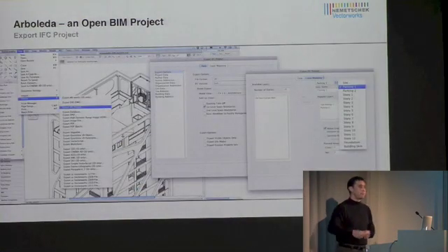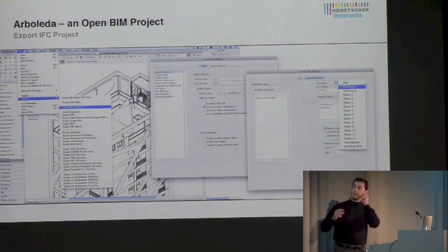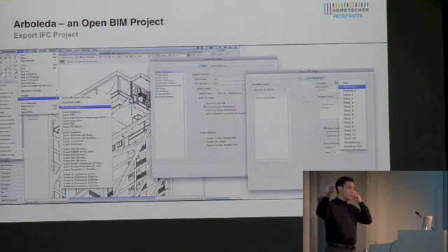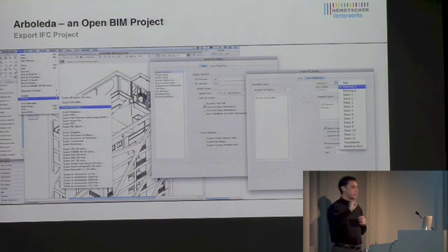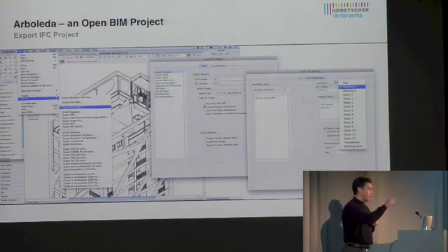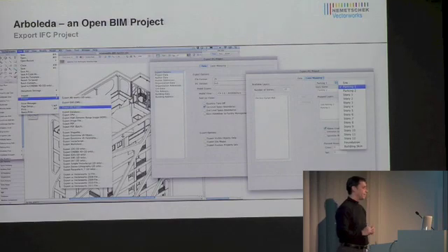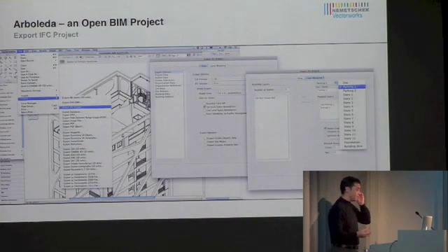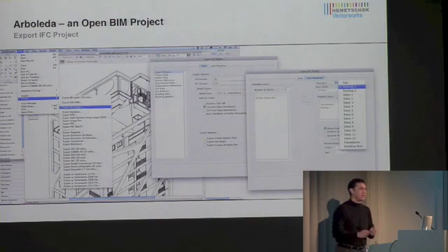So once everything is ready, we export this project to an IFC, and please pay attention to the middle window. You see a little box that says first phase boundaries, and that is the key for sending this file for testing into energy analysis software. First phase boundaries, that was a key. We didn't actually know about this feature until we decided that it was time to see if we can actually do this with another software.